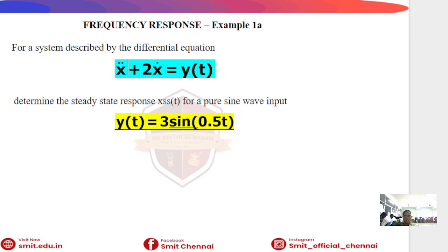Then the change in slope column. For the first point there is no change in slope. From the second row, we add these two values to find the change in slope. Likewise, we continue till the table is complete. Then we choose the low frequency, corner frequencies, and high frequency, which we analyze for this Bode plot.